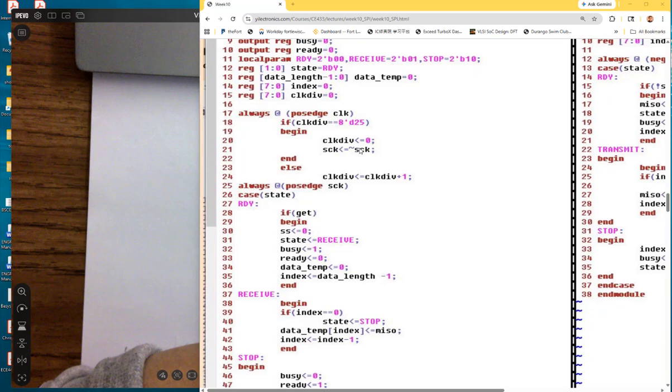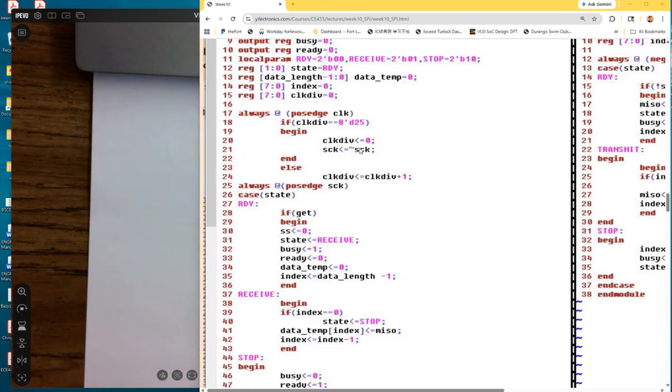So whatever you write into the FPGA, you synthesize it and implement it onto the FPGA, and that will provide the clock for both. Don't imagine that there will be a magical clock coming from anywhere. If you put a 25 over here, it's going to create a 2 megahertz clock for your ADC. So this is going to drive your ADC's clock and do all the conversions. And you need 16 clock cycles to complete one data conversion.